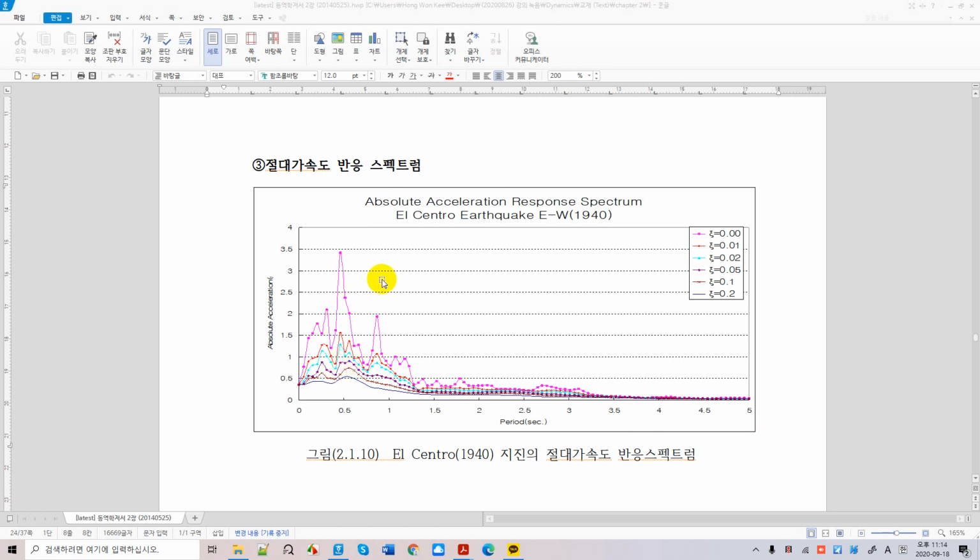If you don't have any damping, which is 0 here, your response is very big, huge, right? And the building will not stop easily. Then you increase your damping ratio from 0 to 20%. 20% is the lowest curve. Why? Because your building's behavior, performance, or accelerations get very small when your damping ratio gets very big, like 20%. So look at that.